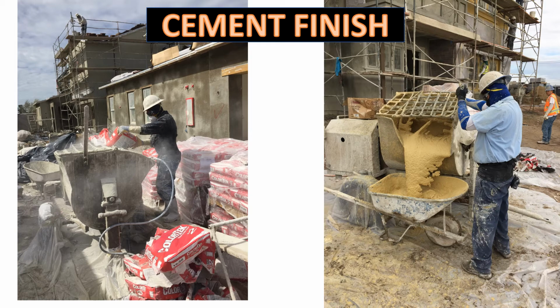The cement finish should be mixed a little stiff for the first 10 minutes, then let stand for a few minutes, and then a little bit of water added to get the desired consistency to dump the mix. This helps break what is known as a false set. Breaking the false set in finish coat cement plaster results in greater working time and enhanced workability. The blade should then only be turned on to dump the material.